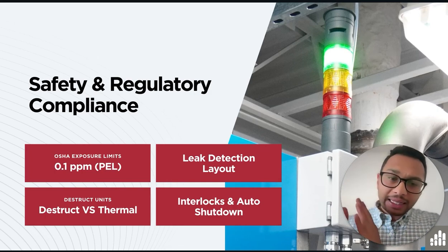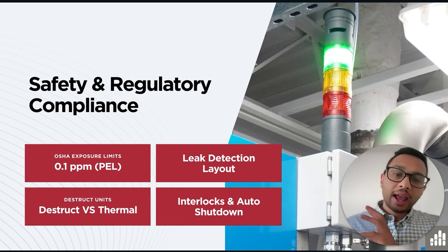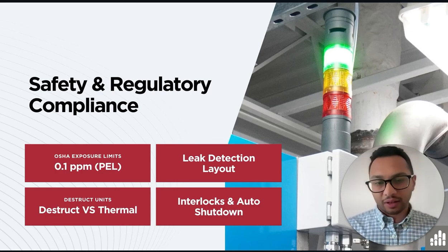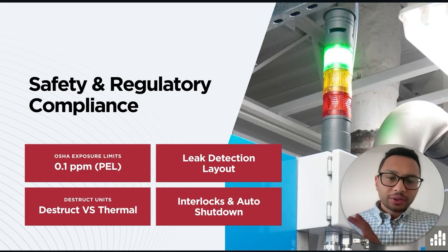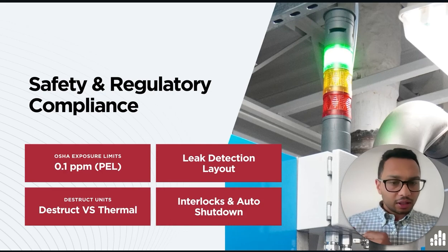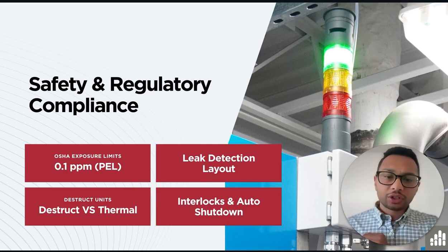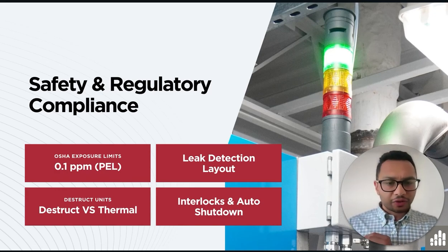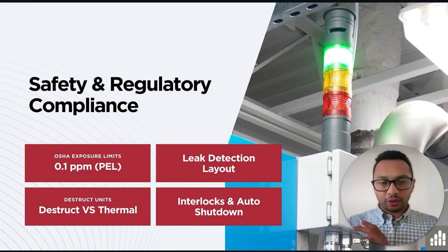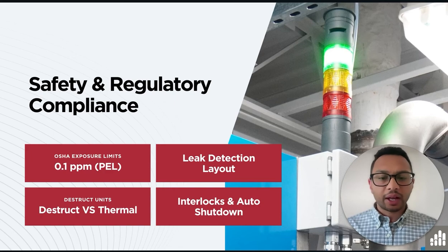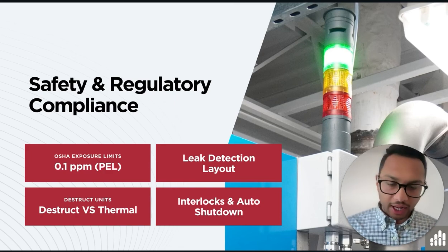Enclosures are completely air sealed, and air handling systems are also designed to make sure that we can manage the ozone off gas safely. On the ozone destruct side, we use either a catalytic or thermal destruct unit, and this is used to destroy any excess ozone that's left over. The catalytic destruct units are energy efficient and are suitable for higher flows.